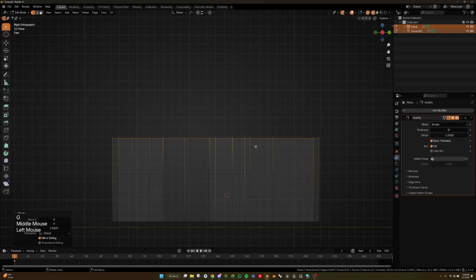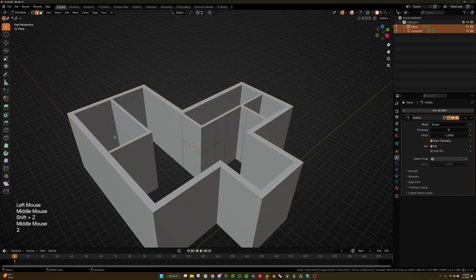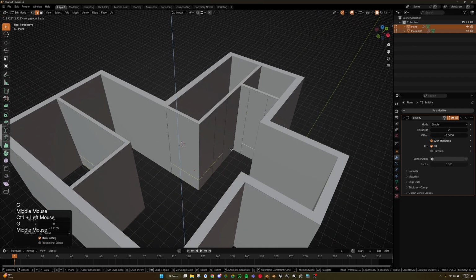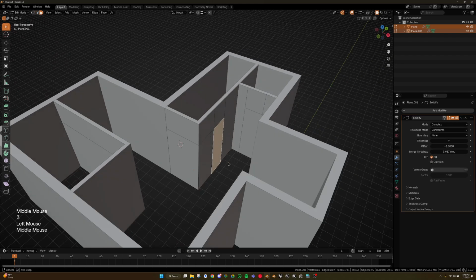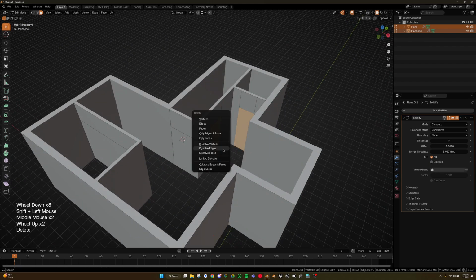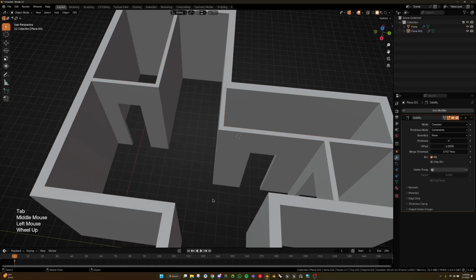And then we're just going to move this up like that, and then click these. So now it should be taken off. So now when we move it up, we can do 6 feet, 8 inches. There, now it's correct. And then you select these faces, and then you can delete only faces right here. And there you go, there's your opening.